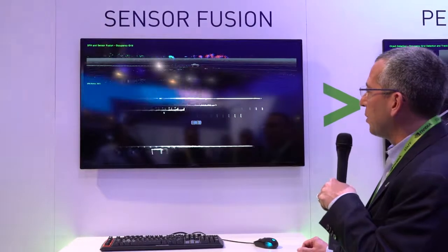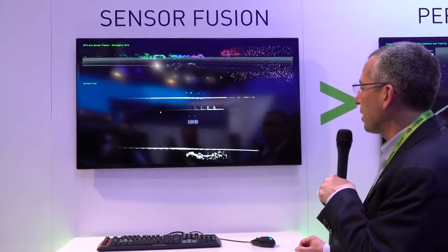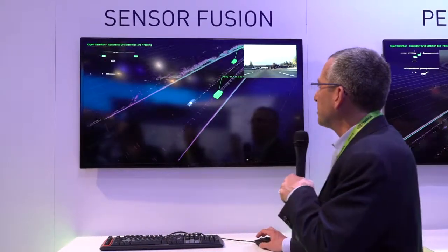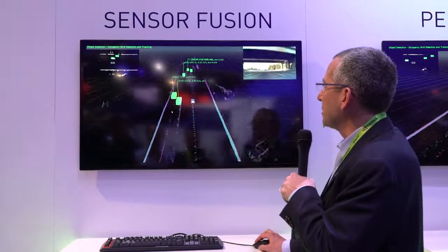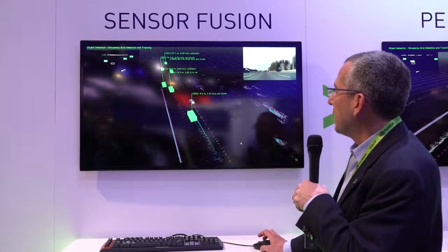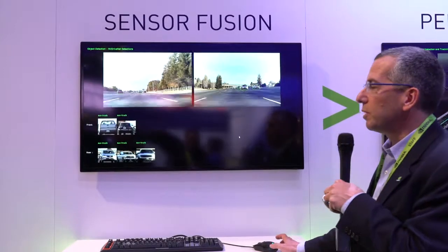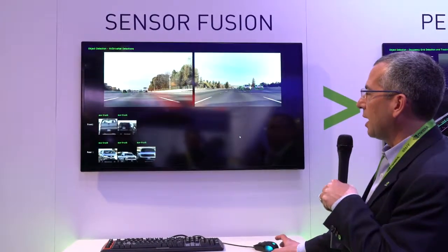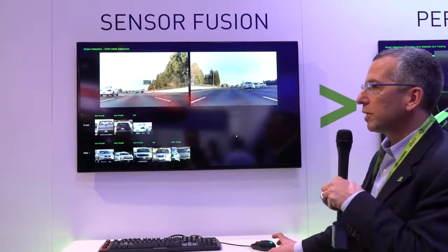algorithm to define points in 3-dimensional space and couple that with the LiDAR information of the other vehicles that we have. From that, we're able to extract a lot of information about what's happening around our vehicle, so we can essentially detect other vehicles and classify what those vehicles are. So using our deep neural network, we're able to identify all the vehicles in the scene in real time and understand more about what those vehicles are.